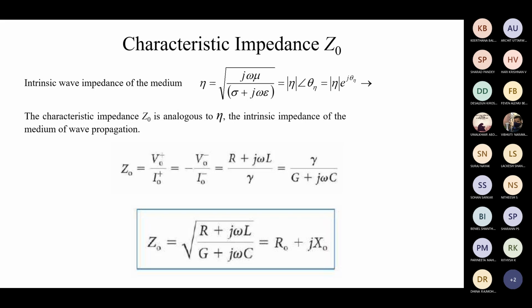and the characteristic impedance. That is why, if you look at transmission line theory in any notebook, they draw the transmission line as two lines, and then mention alpha, beta, and Z0. These three values are put in a bracket and kept inside the two lines, not at the top, not at the bottom, exactly in the middle. Which means that within this starting point to end point, if there is a transmission line and the wave propagates in it, this can be described by these three properties: the primary two properties, alpha and beta, and the secondary property, impedance.